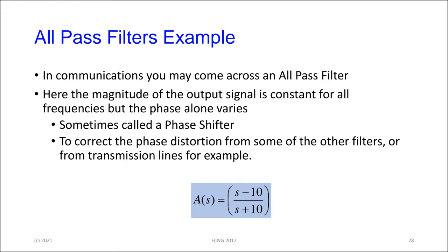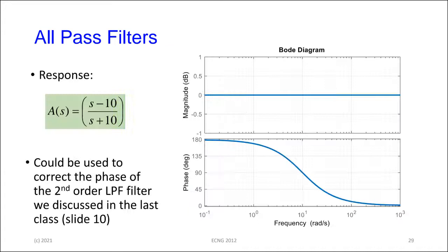And if you look at the transfer function here, it's a single pole. This one is a first order, so it has 1 zero and 1 pole. The second order has 2 zeros and 2 poles, and they are almost complex conjugates when you design them. The response of that filter looks like that.